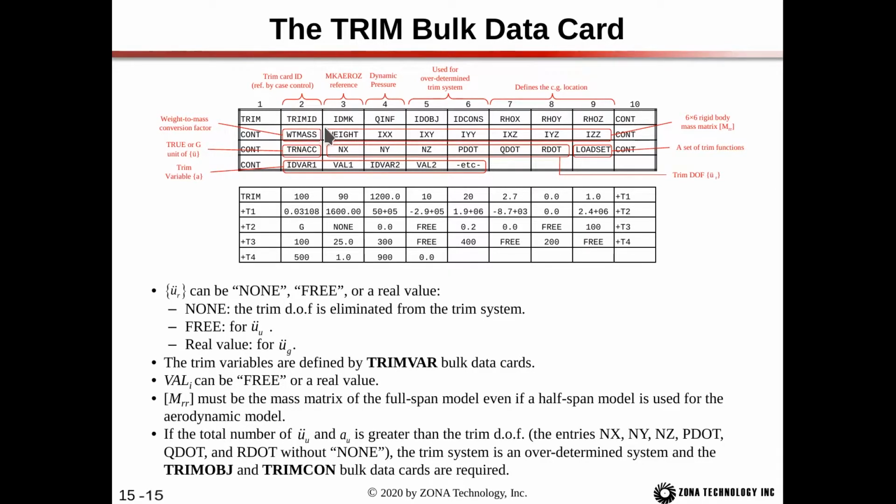But if you're using SI units where your model uses meters and kilograms, and so your weight field is actually the mass, and then your inertia terms are all in terms of kilograms, then weight mass would just be 1 because the remaining terms are actually mass.